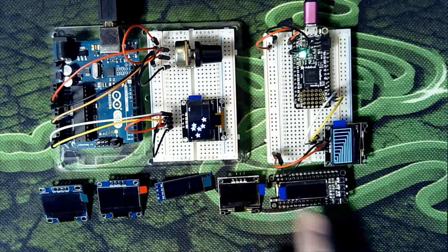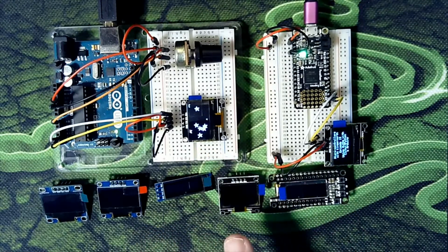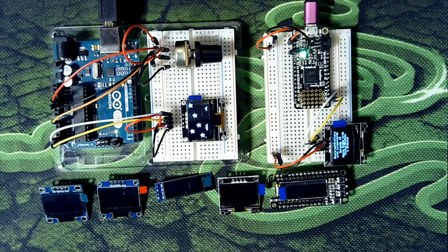These all work with I2C. Now, we talked about that early on in the shows, probably somewhere around episode 4 or 5. We looked at I2C as a communication protocol, which makes it easy to hook up because there's only 2 wires that go back to the actual microcontroller, and then 2 for power and ground. So they're pretty simple to wire up, but I'm going to show you some of the pitfalls.